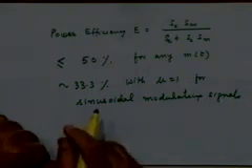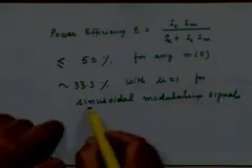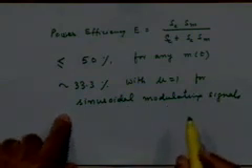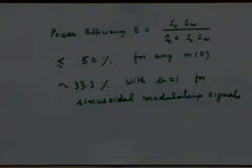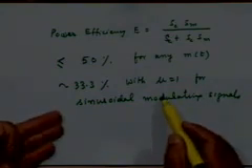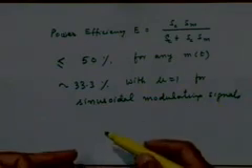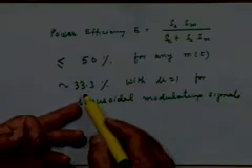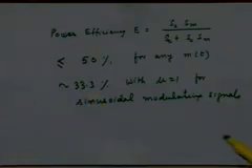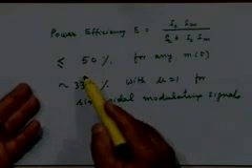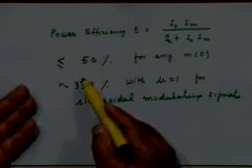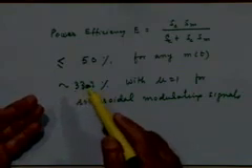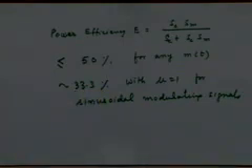Right? So if your message is the one in which m(t) is a low frequency sine wave, and the modulation index is larger, the larger the power efficiency that you will have. So the largest power efficiency that you will get in this case is about 33%. In general, for arbitrary waveforms, it cannot be more than 50%. That can be sure, right? It has always got to be less than 50%. So therefore, there is a significant power inefficiency involved in this process, right?